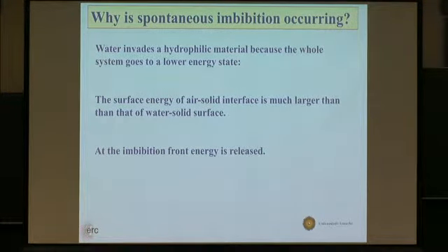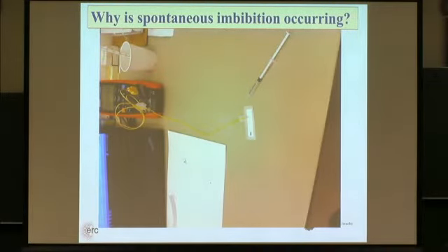So as I said, the reason that water invades a hydrophilic material is because the system goes to a lower energy state. The surface energy of the air-solid interface is much larger than that of the water-solid interface. And at imbibition, that energy is released and the system goes to a lower energy state. And you can ask yourself, what does happen to that energy actually?